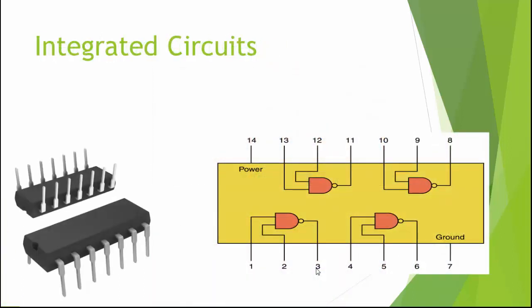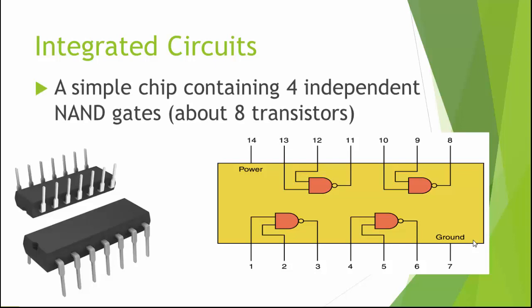So we can view the chips, and this is our first look at a real one here. We can view these chips in terms of the decision making that they do. So we're back to our logic gate picture. This integrated circuit contains 4 NAND gates, which are created by 8 transistors in a single 1 centimeter long package. So we can view it from the logic gate point of view. Notice we have 14 inputs and outputs here, and 14 pins on our chip.